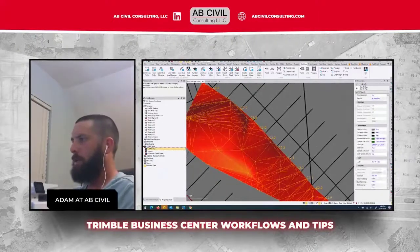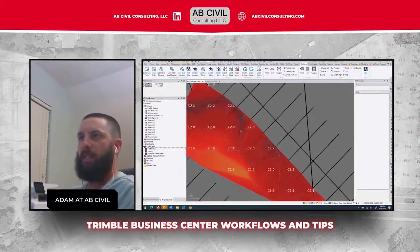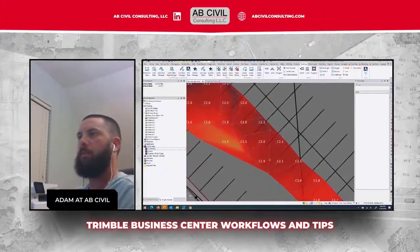But I can take this and change that cut fill map. If I made this 10-foot spacing, you don't get a lot of information. You can see this dark area here, and a lot of times you wonder, what's the most cut there is? So you just come over here, and if you look, 2.24, 2.27, 2.28, I can just hunt around for that highest number. And it's live scrolling that surface.